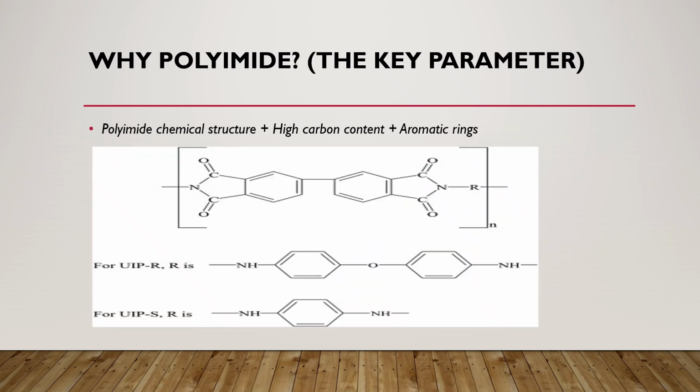So, why is polyimide the most common substrate used in LIG? There are basically two reasons. One is high carbon content. Firstly, it has very high carbon content. More carbon means you will get more graphene. So high carbon content is the main reason for using polyimide as a LIG substrate. Different substrates, for example textiles, wood or cloth, even food, which can have high carbon content, can be turned into LIG.